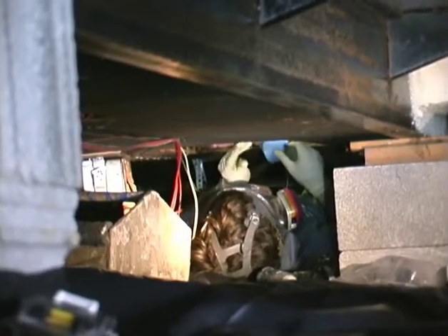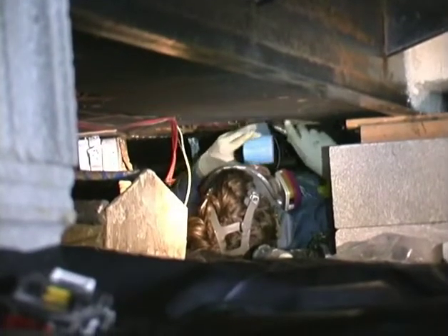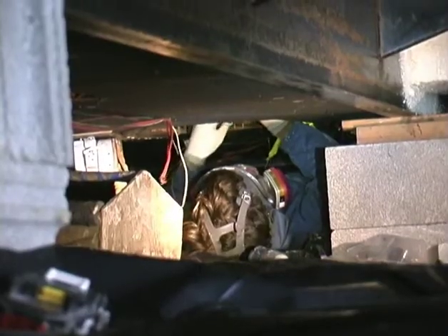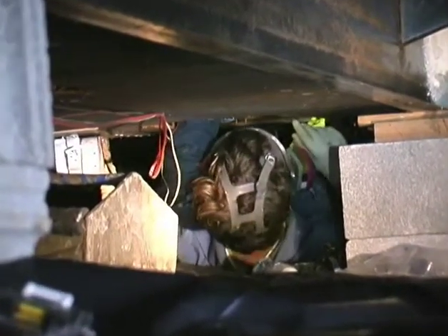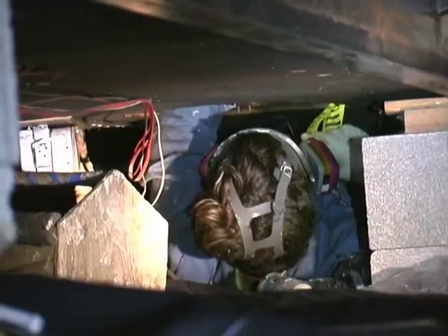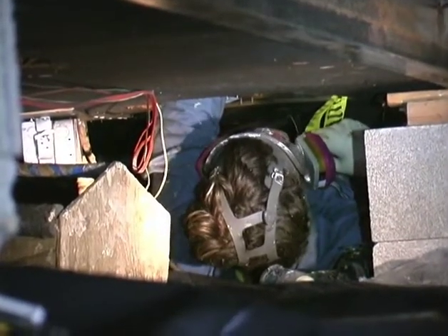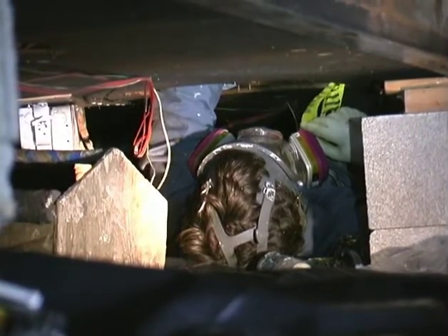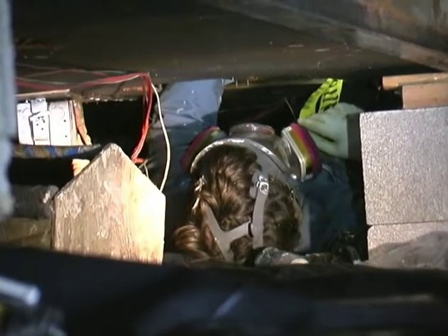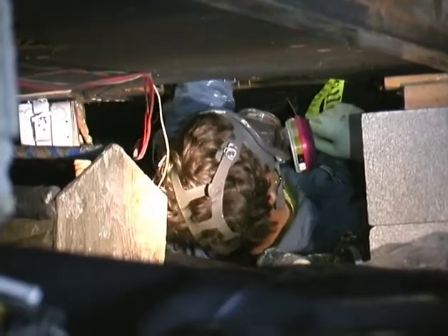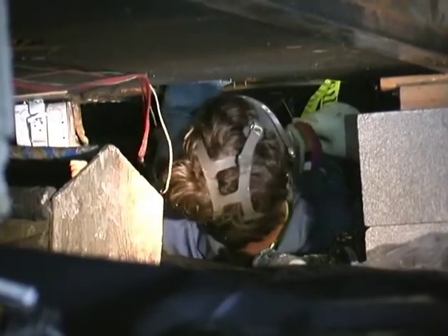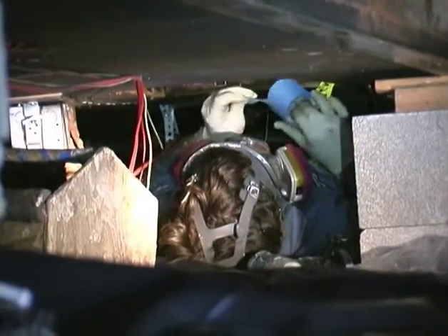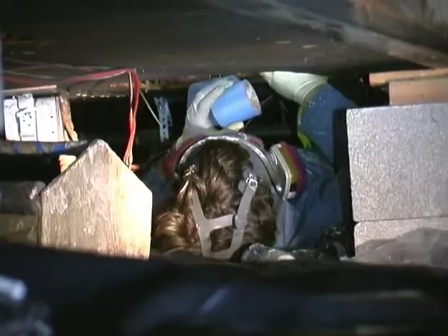Our technician Jake is working on the most important thing to seal on a mobile home duct system. It's the furnace to trunk line connection. It's the point of highest pressure in the duct system, therefore it'll leak the most. Jake has had to cut through the underbelly material there and access the bottom of the main trunk line. Then he cut a 3-sided cut in that and folded back a section of the main trunk line so he could access where the furnace connects to the main trunk line.